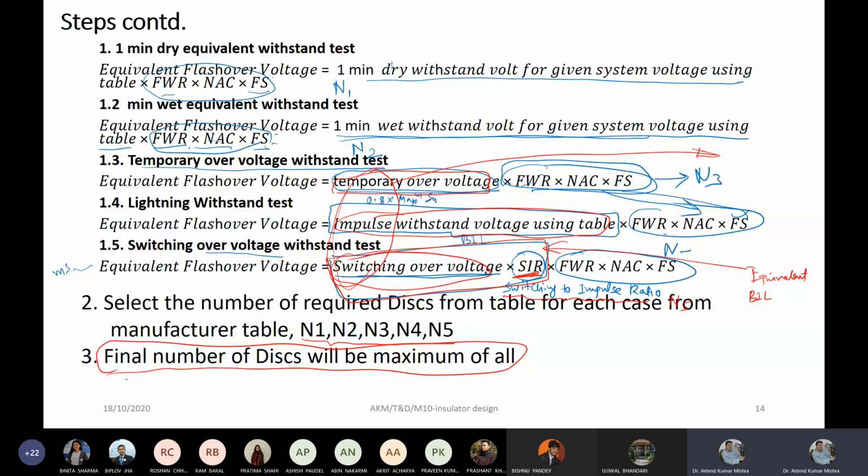All these three voltages are kept such that one is not far away from the other. Otherwise, the insulation cost has to be increased only for that value. And there is always a control. That's why control of the lightning, switching overvoltage or temporary overvoltage is needed, and not all controls are applicable in all conditions. Particularly if we go for high voltage lines.